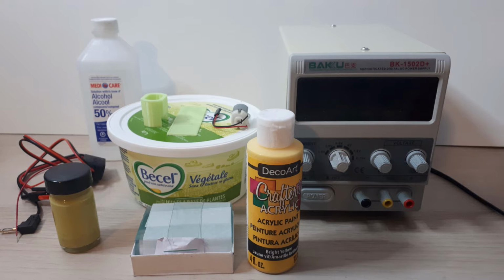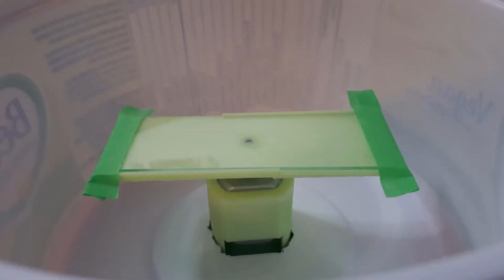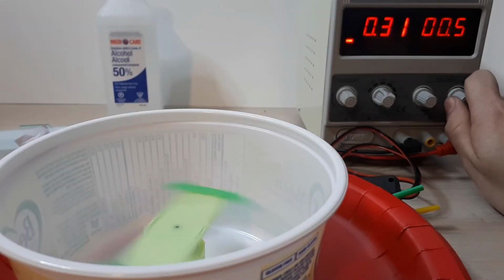This one here is a Type 130 micromotor, a variable DC power supply, though a battery will work. Type 130 motors typically require 1 to 4.5 volts to operate. Microscope slides, though any rigid flat surface should suffice, a medium container to house the spinner. 3D printed mounting fixtures are used here, though strong glue would also work. Painter's tape is optional. The motor is inserted into the mounting fixture and secured into the center of the housing container. A microscope slide is placed onto the mounting fixture.